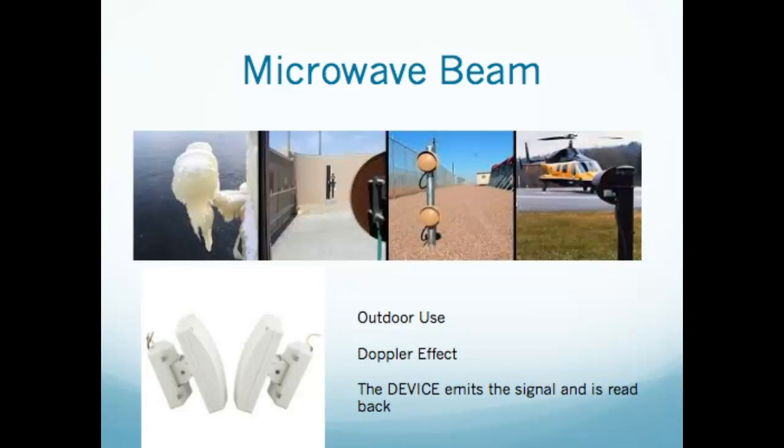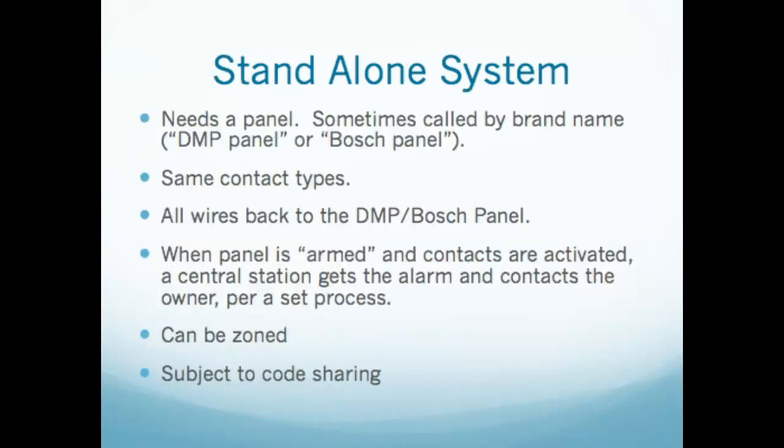They're really just an on-off. They're telling you something has changed. If this happens, then do this. If somebody walks in between the microwave beams, then send a signal to your alarm system. If these two doors separate and the reed switch opens up, send an alarm to my alarm system. It's always an if-this-then-that type of scenario. Those are the ways you can detect alarms. Those are your switches. So now we know we have alarms and we can put them through.